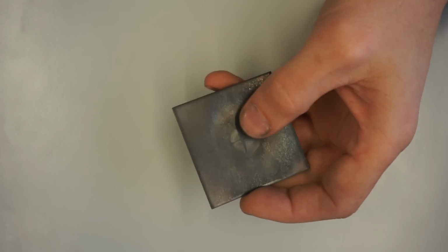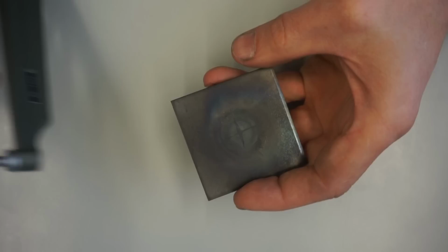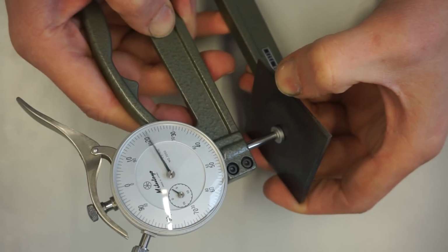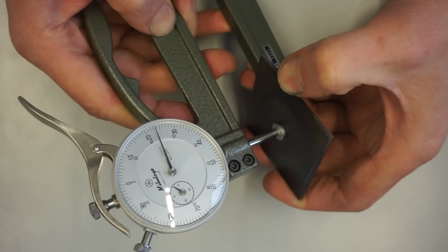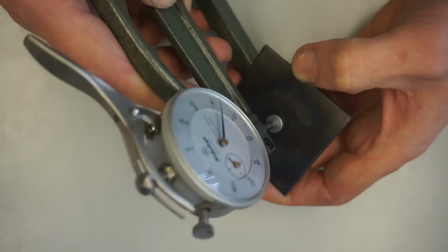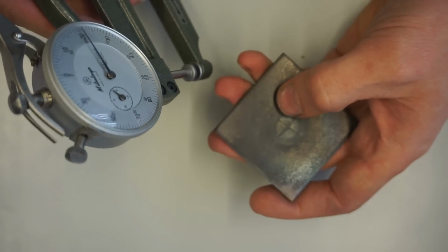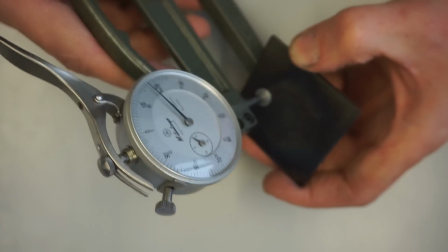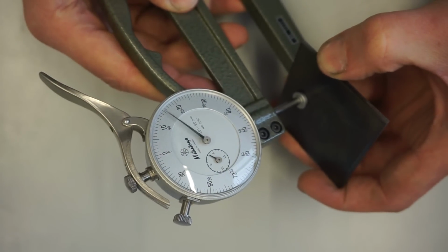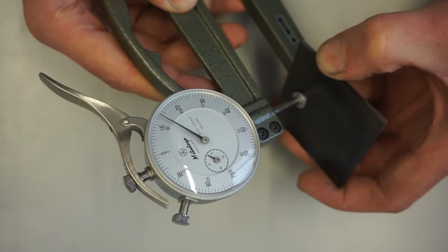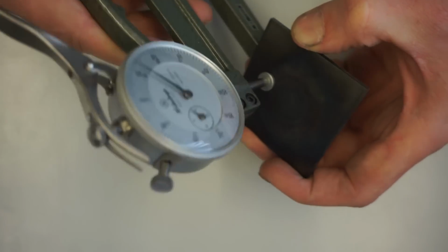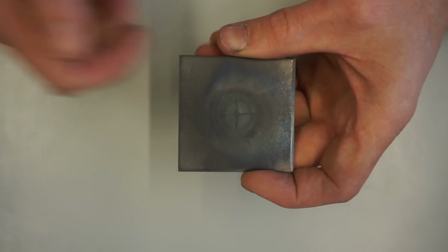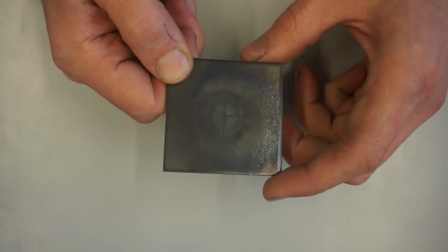Now let's measure the thickness a little away from the heated spot center. Again, as we measure the heated spot center, we have the 3.22 millimeters, and let's go to the area where the discoloration begins, like here. And here you already see that we have the initial thickness of the sheet again, 3.12 millimeters. So what we learn from this is that the thickening is almost limited to the area which was red hot.